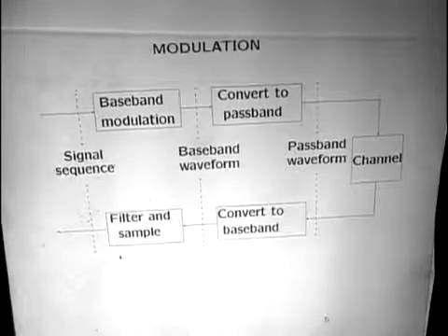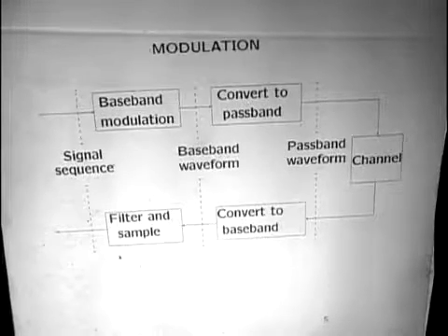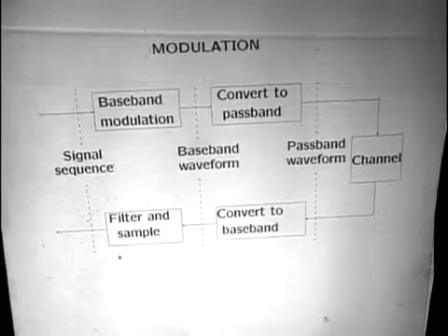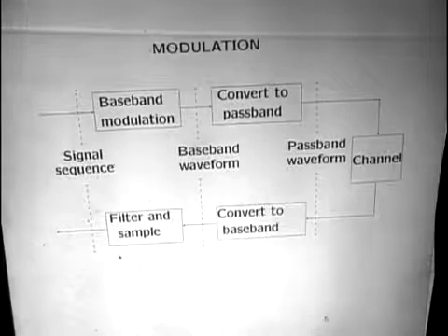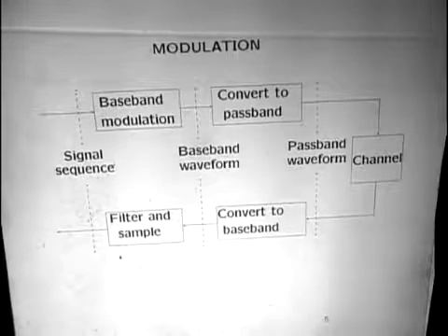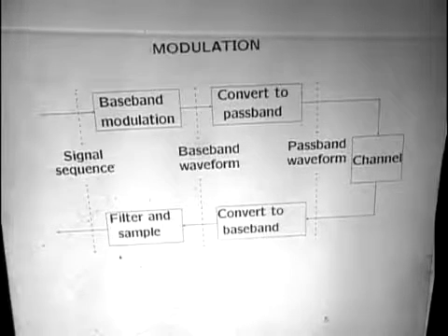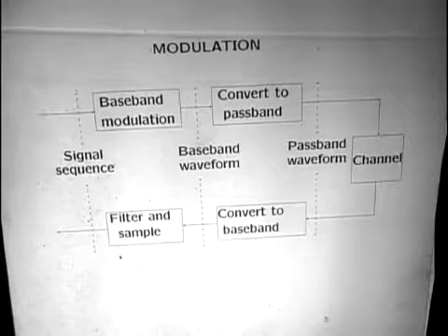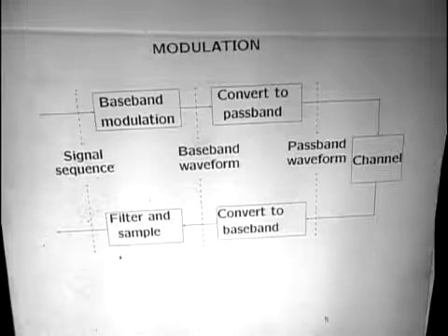I mean, why do we have to turn it into passband anyway? Well, if you did everything at baseband, you wouldn't have more than one channel available. I mean, wireless, you know, you have all these different channels. The way it's done today, you use something called CDMA, where you're not breaking it into narrow channels. But you should understand how to break it into narrow channels before understanding how to look at it as code division multiple access.